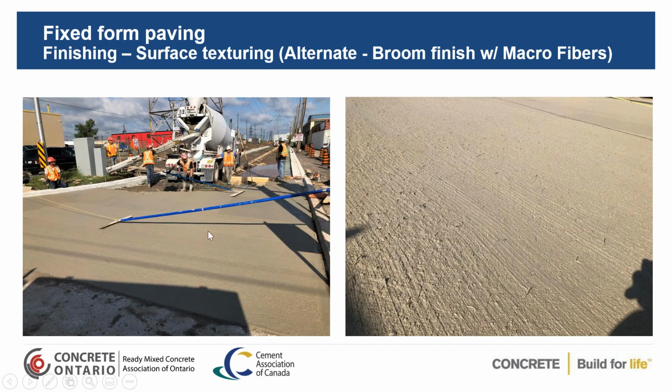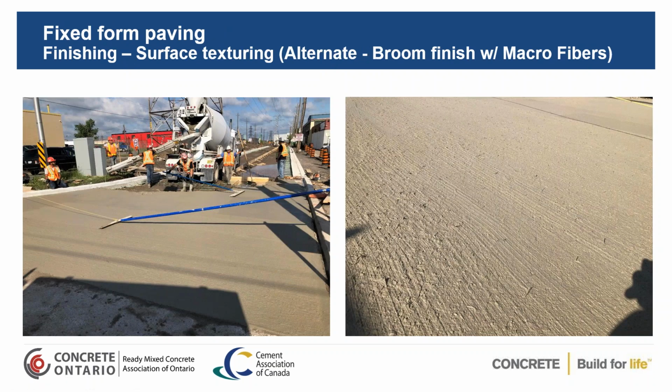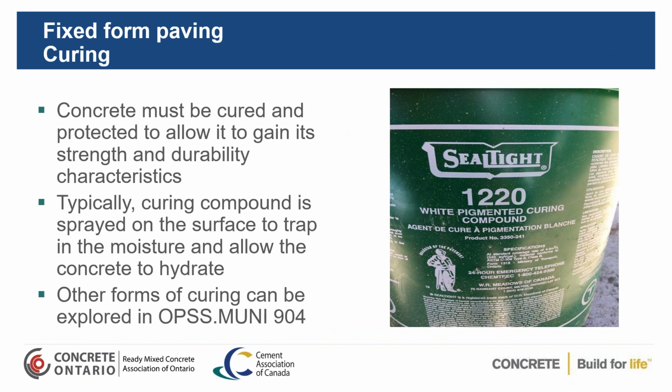And this is just another picture of an alternate surface. Now this is with microfibers. You see it's a little bit rougher surface because the fibers are being brought to the surface. And in this case, an alternate broom surface. Went the wrong way. So next thing is curing.